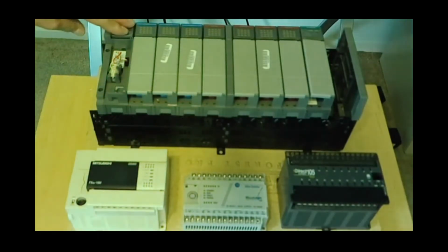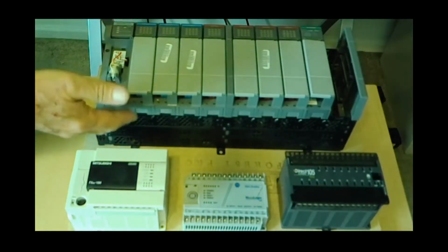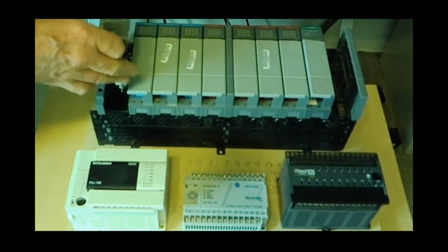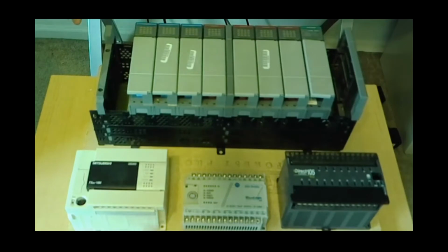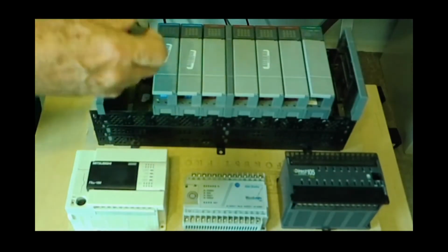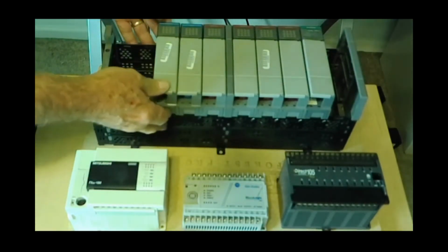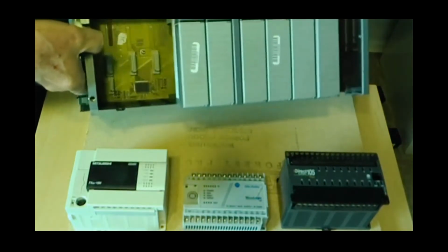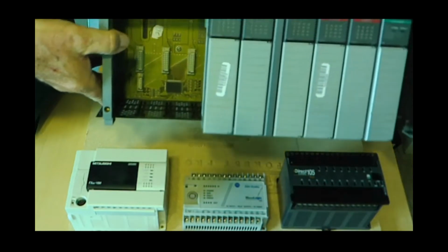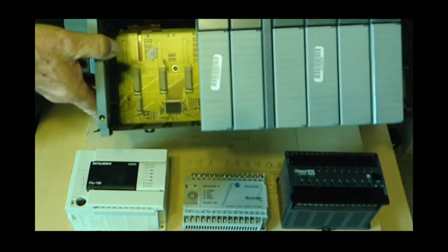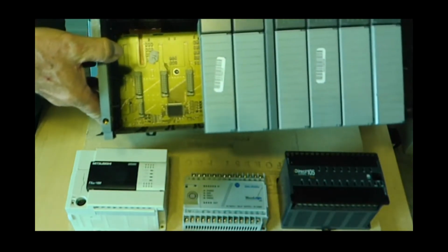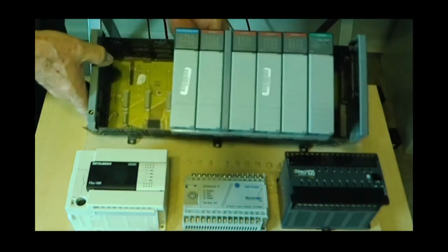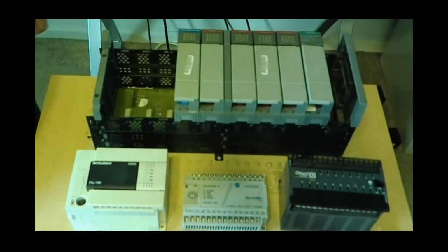First of all, this PLC is referred to as a rack system. And why it's referred to as a rack is everything right here removes. The CPU removes, the input and output cards are removable, and inside in the back what we have is called a backplane. This little backplane, you can see there's not a whole lot of electronics on there. This is mainly a communication bus where the cards themselves can communicate with the CPU.